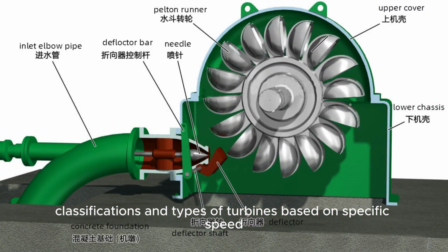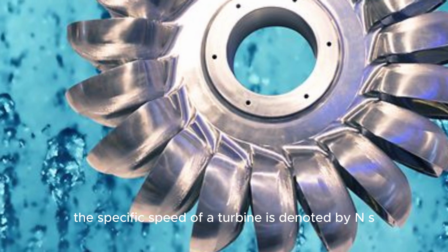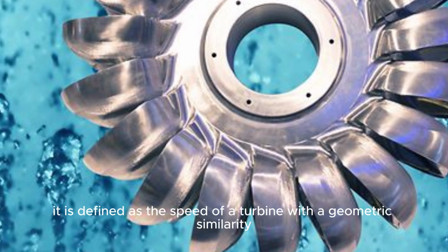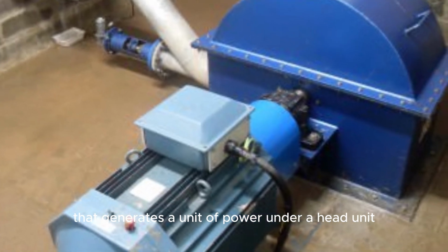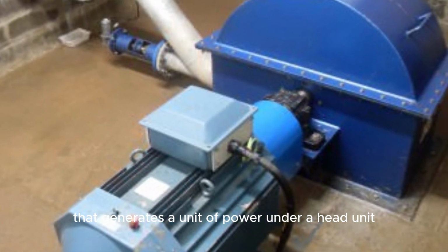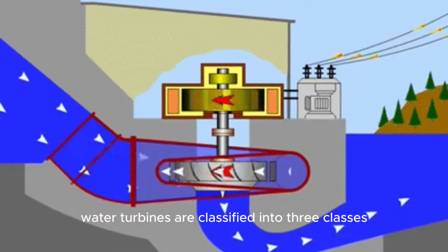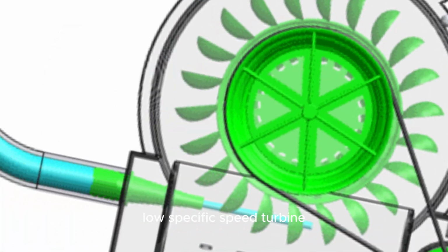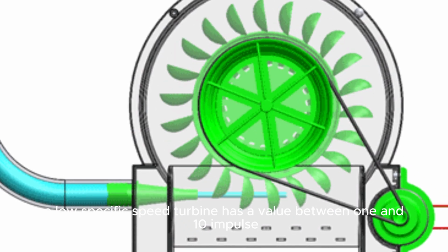Classifications and types of turbines based on specific speed. The specific speed of a turbine is denoted by Ns. It is defined as the speed of a turbine with a geometric similarity that generates a unit of power under a unit head. Based on this parameter, water turbines are classified into three classes. Low specific speed turbine. A low specific speed turbine has a value between 1 and 10.